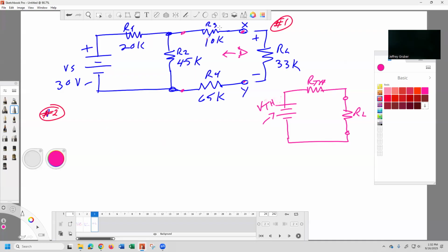What about an ammeter? It's the exact opposite. It's a really, really, really small resistance. Some current flows through it and you see a drop across it because you don't want to change the current of the circuit. So if you think about it that way, then it makes sense. It's like, oh, okay, some current comes through here and I'm seeing the voltage across here.